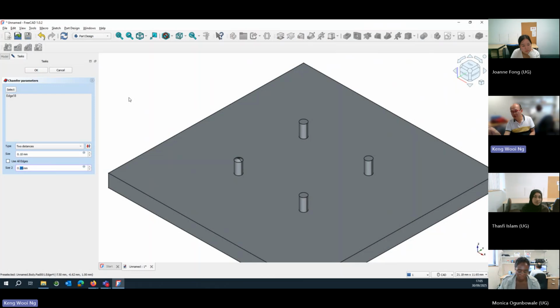However, if you put 0.25, the program doesn't like it because it can't deal with the fact that this dot is nothing. The dot has to have a size. The middle bit, right? The top part of this cylinder has to have a size. If you specify this width as 0.25, it doesn't like it because then the peak becomes a single dot with no size. So instead of saying 0.25, I make it 0.249. Then the software is happy. It can do it.